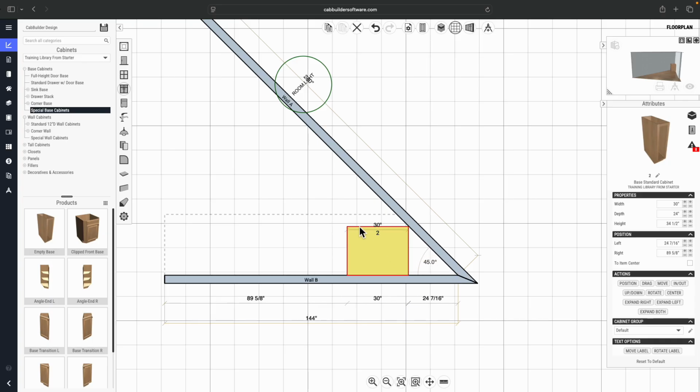Well, I would need to go within the cabinet and edit its perimeter to have the back left edge extend out, looks like another 24 inches this way. Now I can either do that by creating the perimeter from scratch, or I can edit the existing shape. I prefer just editing the existing shapes.